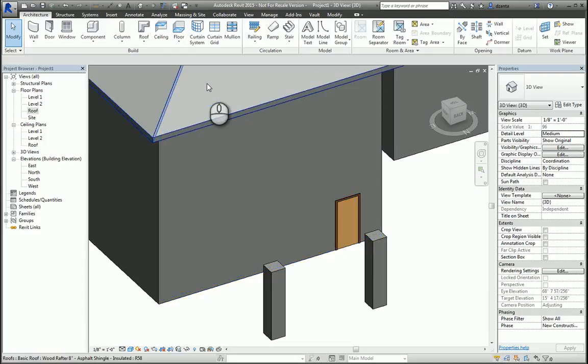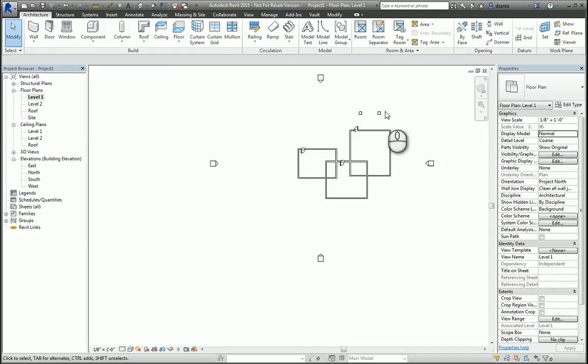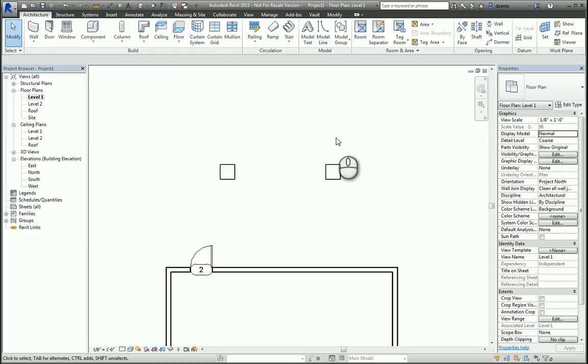For example, maybe you need to create a roof that has a strange profile that's going towards the building, something like a basic carport. In order to do roof by extrusion, you want to make sure that you have a couple of things already in play. For example, the first thing you'll want to do is have a reference plane. This makes it a little easier for you to create the profile on that plane and adjust it accordingly.